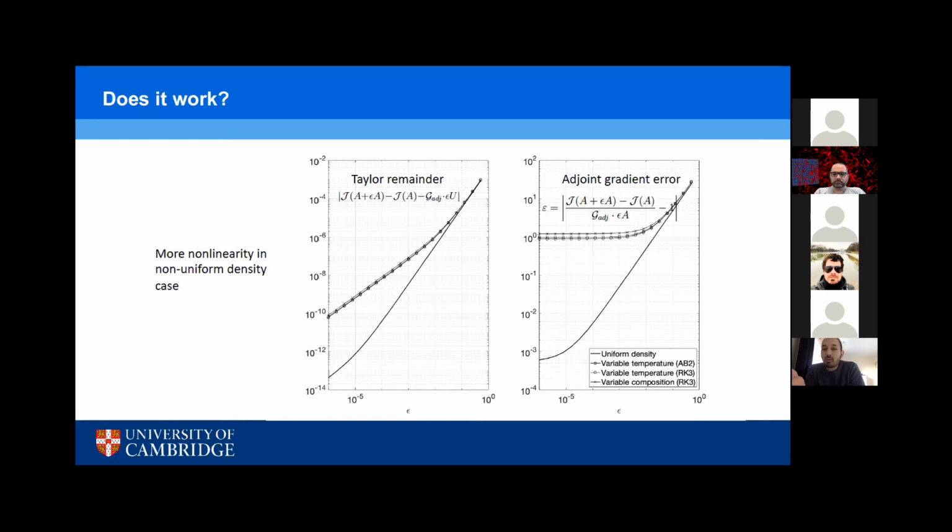The continuous adjoint solver will only give the exact gradient as the mesh resolution approaches infinity. So this is all part and parcel of the errors in the discretization between the forward equations and the adjoint equations. Combine that with the fact that, yes, in the Low-Mach number case, it is a bit more ill-posed.